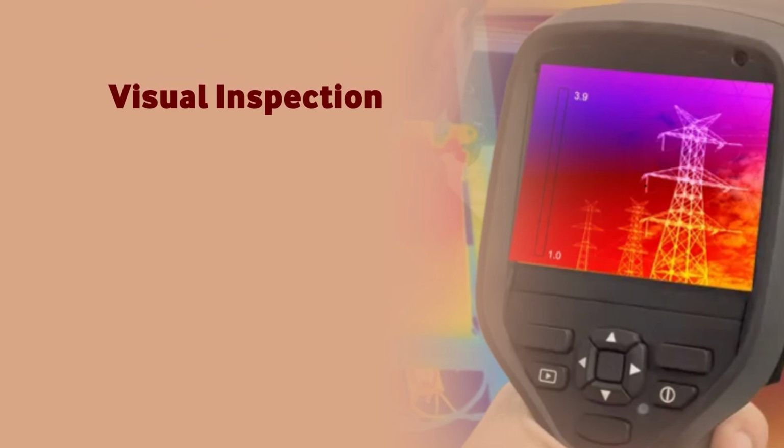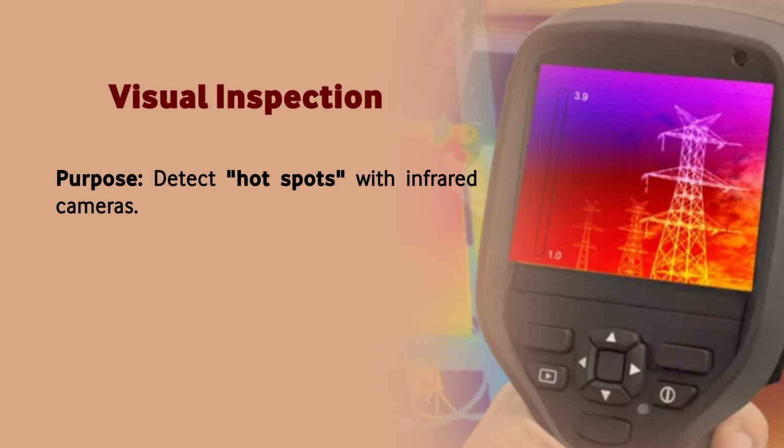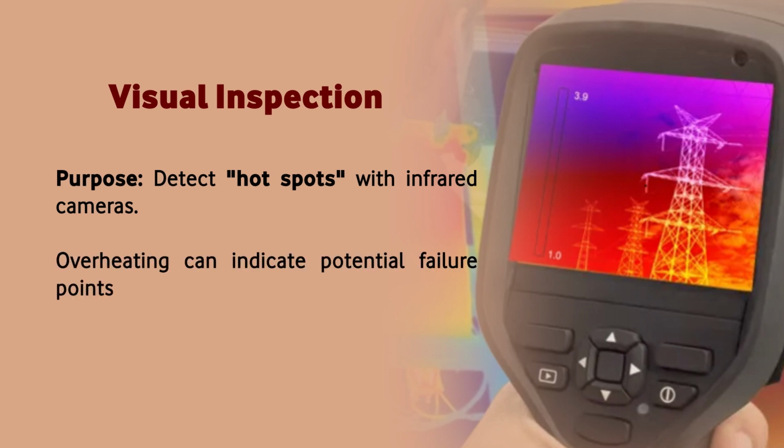Next we will see thermographic scanning. Thermal imaging cameras are used to detect hot spots that could indicate failing components or overloaded circuits.